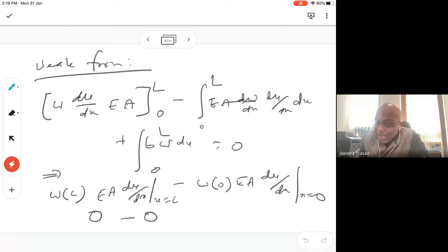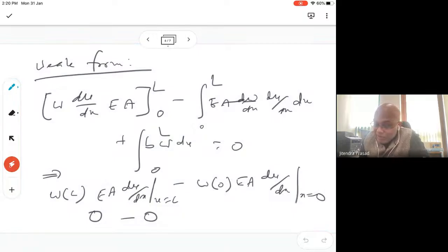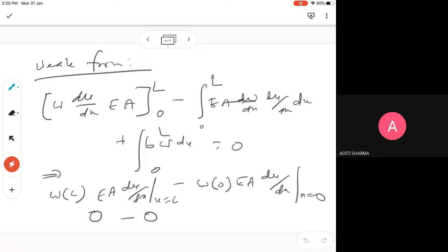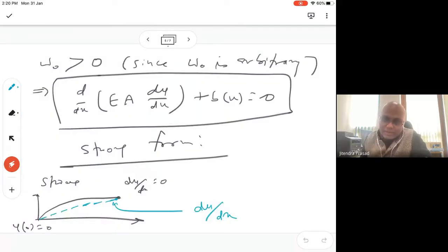So if you write a weak formulation like this one, on top of that we are not writing du over dx at this equal to 0. We are not writing that. So this becomes a single equation and we try to solve it. And sir, our W0 is 0 here, right? Yes, W0 is 0. Those things, when we do, it is easy to solve it. But the solution you get is not necessarily the exact solution. So that's the problem.